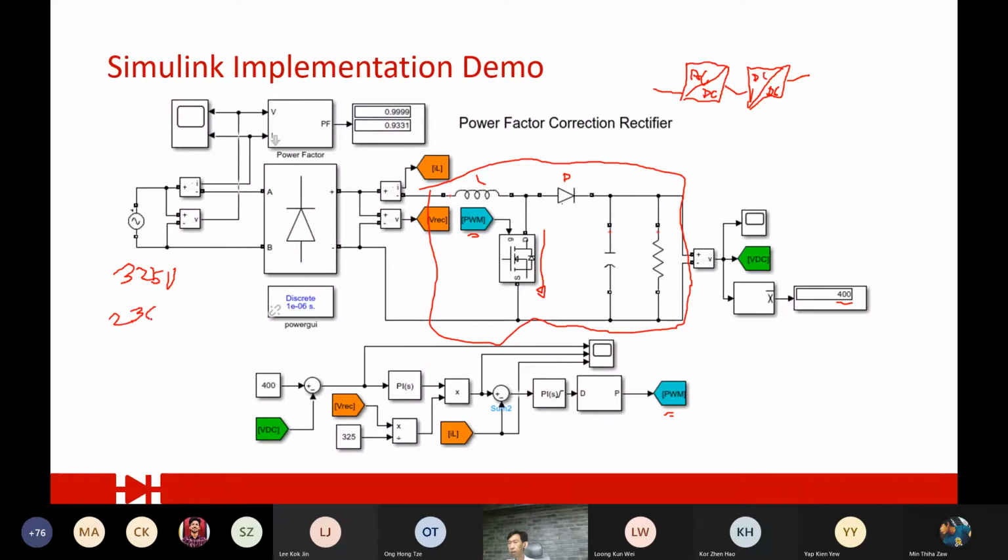In our application, for example, this is a very classic example: your EV battery easily needs 400 volts because most of the time they charge on three-phase. But now your house or the condo you live in is only single phase. Then you only get 230 where the peak is 325. How are you going to get 400 volts? The boost converter is a solution as well.